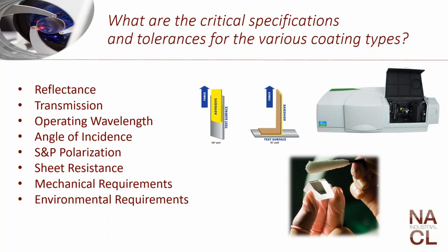Normally to get a good measurement with reflectance, you have a witness standard that goes with your coating run, and you'll usually put multiple witness standards at different points in your chamber along with your production parts. The back side of that surface is frosted, and usually it's painted in an absorptive black. The reason this happens is we want to measure only one surface for true reflectance. If the back surface reflectance starts to come into play, you can skew your readings, and you'll actually display less efficiency in your coating. So a one-side frosted blacked witness chip measures single surface reflection.